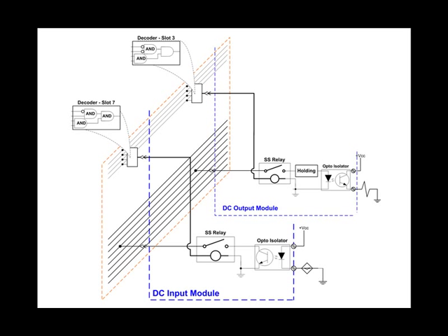One of the most popular PLCs will support 30 slots of I/O. Each slot will support 32 words as inputs and 32 words as outputs. That is a total of 1,920 words, or 30,720 unique bits trafficking on the backplane each processor cycle.